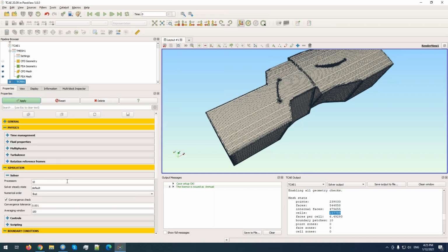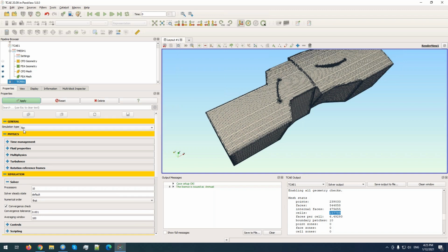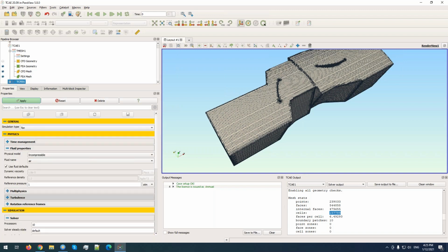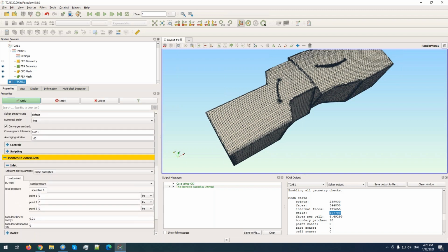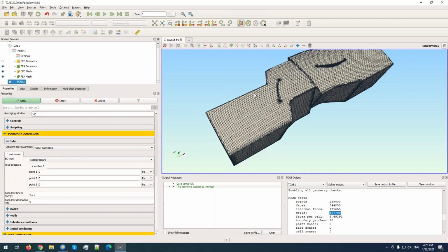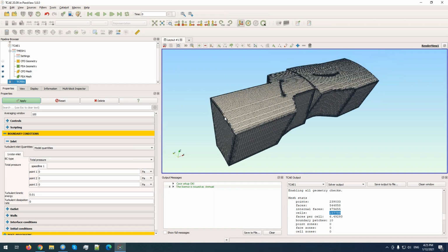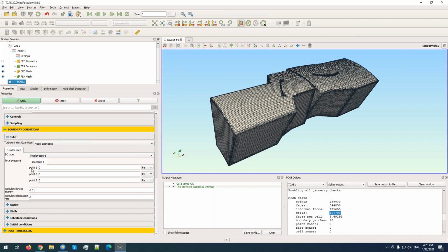After the simulation is finished, our post-processing tools will convert it back into real pascals with the reference pressure of 1 atmosphere. All pressures everywhere will be recomputed back into pascals with this reference pressure added. As a result, at the inlet we will have 100,000 pascals.